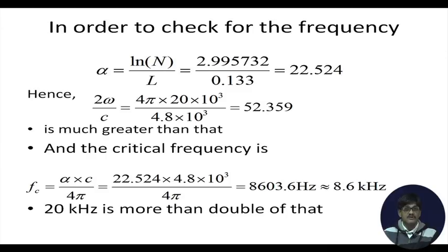But what's the threshold frequency? That is a frequency value below which there will be no periodic motion, and we should generally be 1.5 to 2 times that particular frequency in order to have a safe selection of frequency.